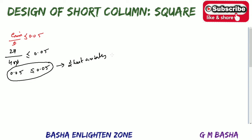Okay, not an eccentrically loaded column. For example, if you get e minimum by D greater than 0.05, at that time you can design a short uniaxial or biaxial column based on the given condition. I will explain those problems also in further classes. Then here we confirm that we are going to design this problem as a short axially loaded column.